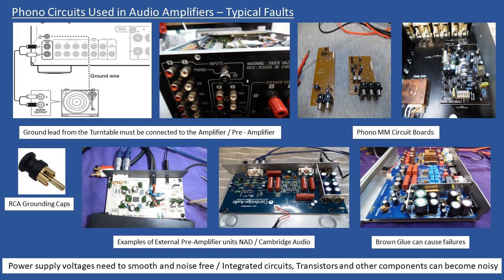So it's like a 100 Hz or 50 Hz power hum, and then you could just amplify it up. It was very common for audio engineers or repair engineers, as we're working on equipment, if we just want to do a quick test, you've only got to put your finger onto the signal part of the connection, and the amplifier will amplify that 50 Hz power hum. So you can fit these grounding caps.